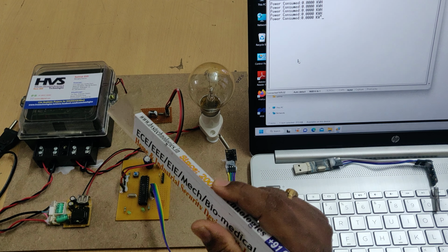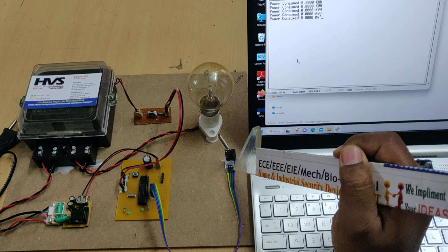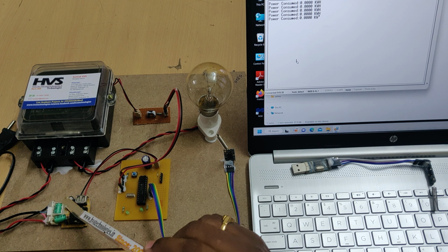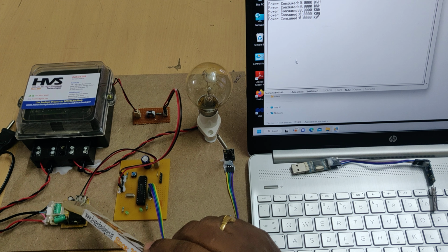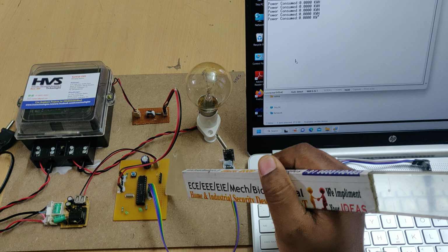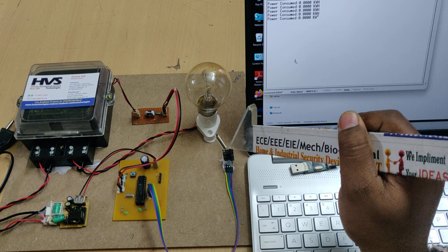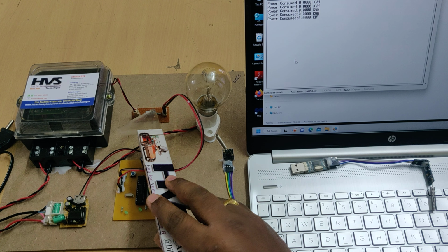but it's going to be 12 volts, while the operating voltage for a microcontroller and RF module is 5 volts. So we use a 7805 regulator on this PCB, and we get 5 volts DC constant. That DC is the input to this microcontroller 28 pin board. From here we distribute it to the RF module and the PC817 optocoupler.